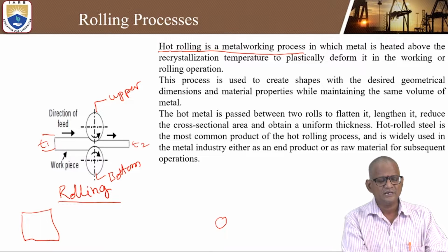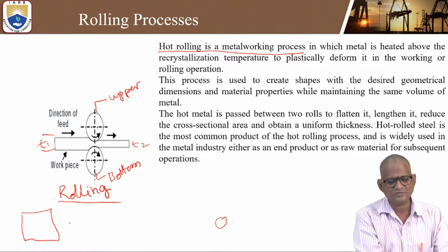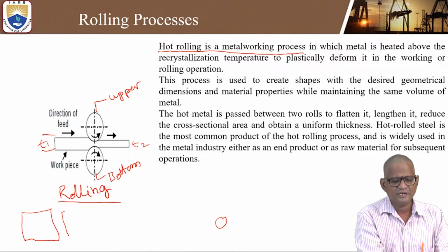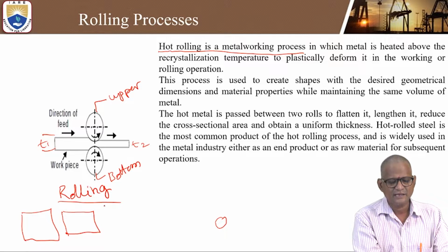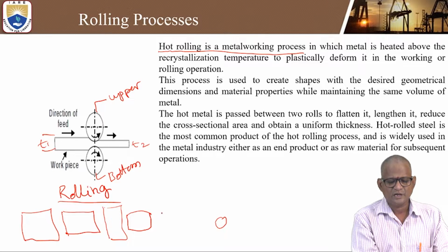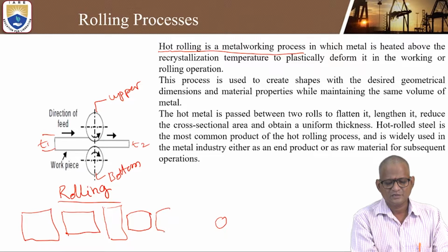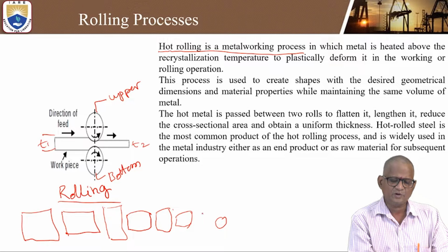So especially here, first this square will be tilted into a rectangle, again it may be formed into this vertical, and some shape can be obtained. Similarly, some different shape forms can be obtained, so that various types of passes are obtained, and finally the circular rod.